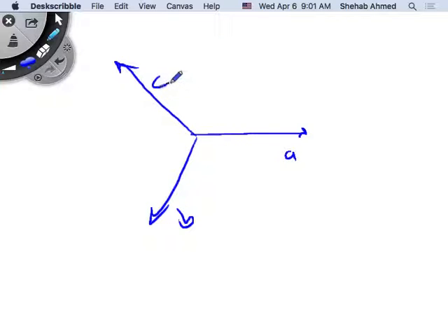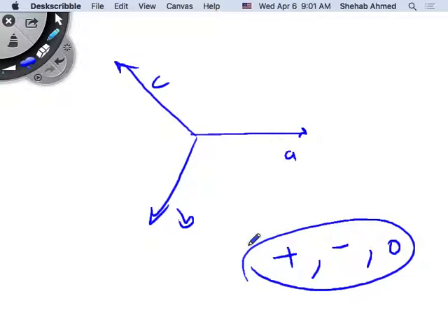I said that if a system is unbalanced, I can take it and chop it up into positive sequence, negative sequence, and zero sequence components. How do you do that? We need a mathematical manipulation to allow us to do that. I cannot go and measure positive, negative, and zero sequence for an unbalanced system. You can measure phase quantities and apply a mathematical manipulation to come up with positive sequence, negative sequence, zero sequence representations of the system.